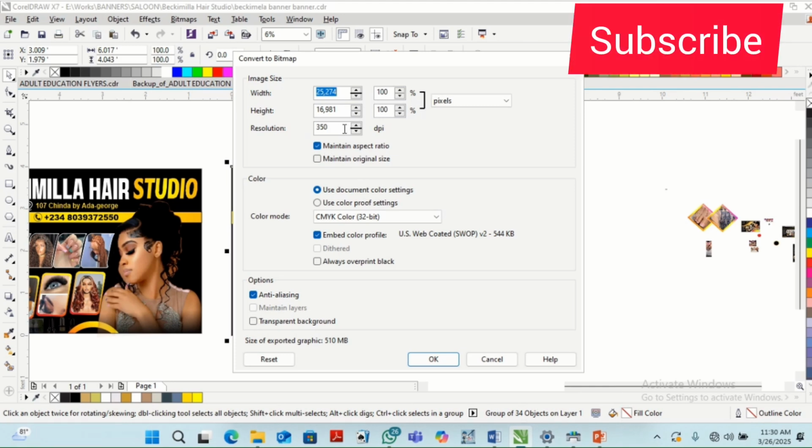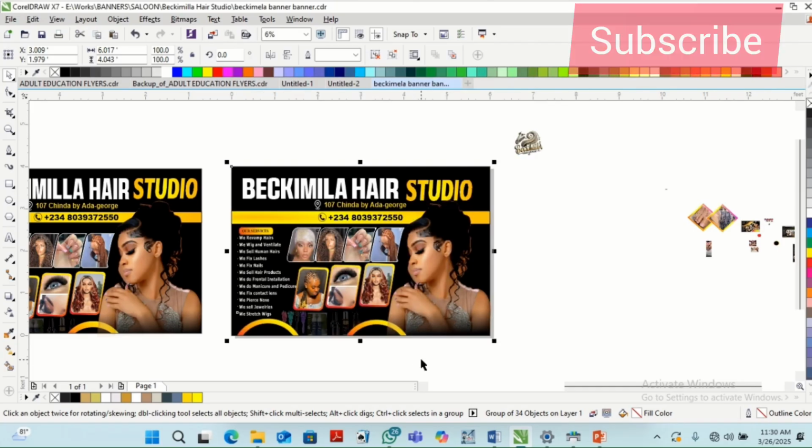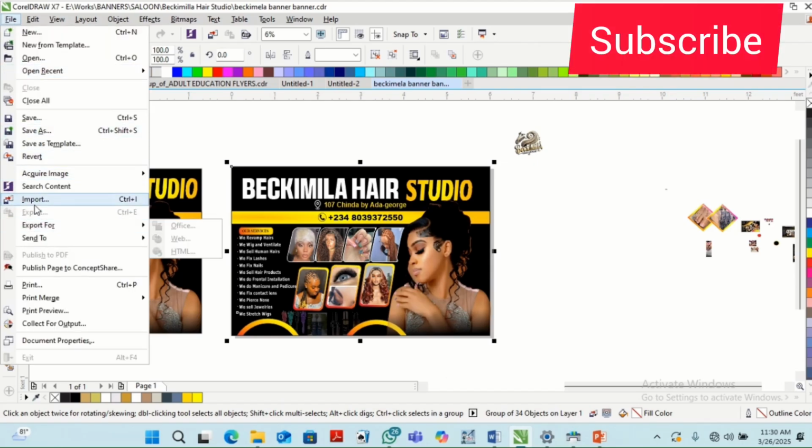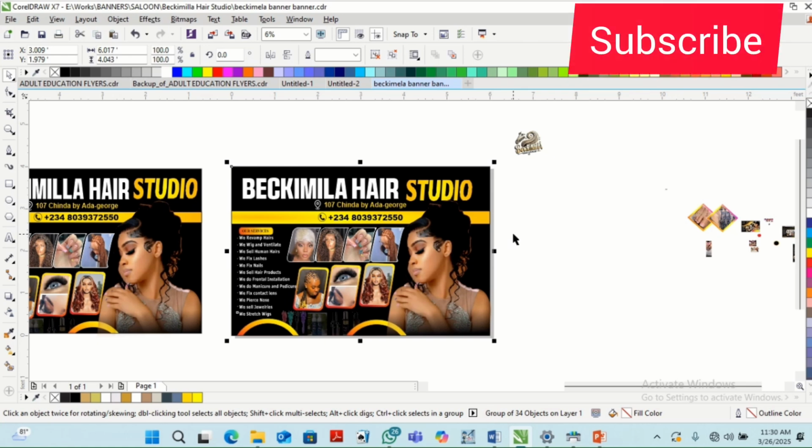Then the resolution, I'm going to reduce the resolution size so that the file will not be too large, because what I'm printing is big. If you are printing a smaller thing, you can increase the size. So I reduce it to 250 based on the size of my file. All right, so now that is all. As you can see, the file has been exported out.